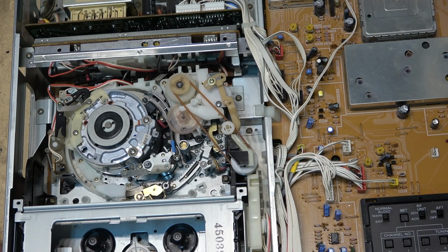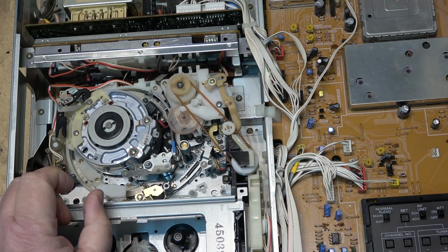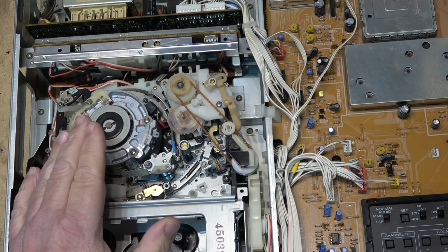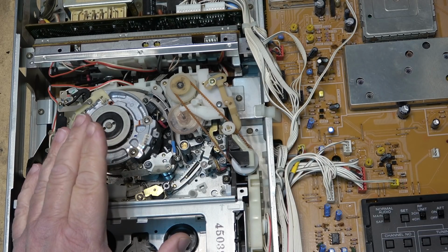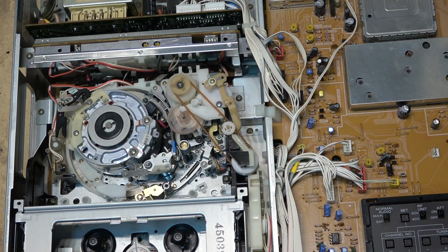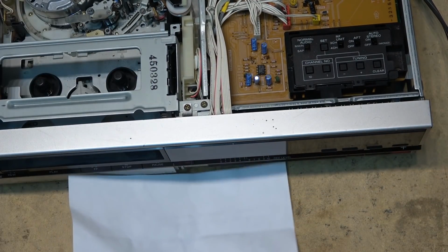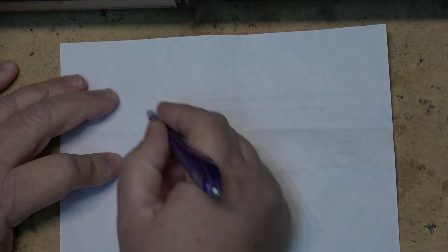When they developed Beta Hi-Fi, what they did was they took a portion, about 400 kilohertz of bandwidth, off of the lower sideband between the chroma and the luminance signal. And this has been gone over in my video on the Sony Beta Hi-Fi training, but I can draw it out here pretty simple. So if this is your frequency,